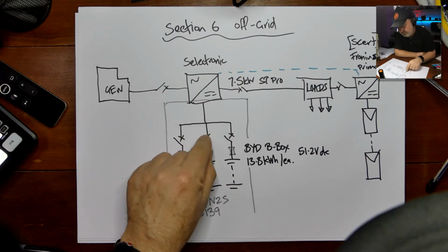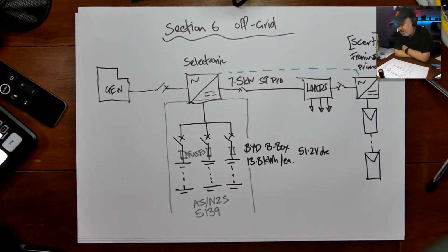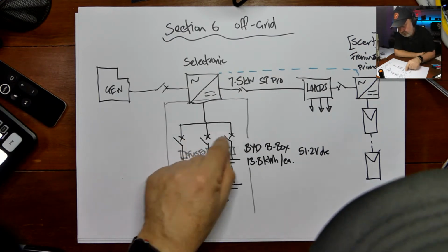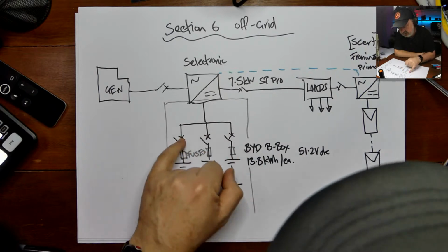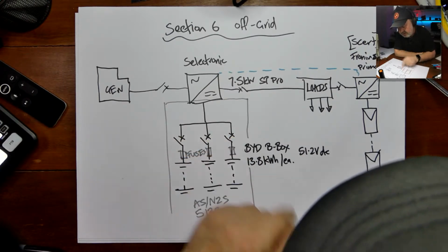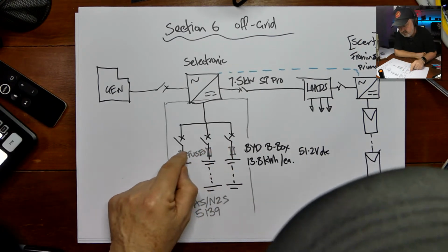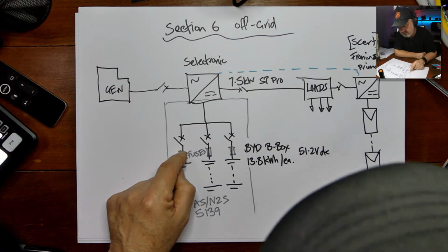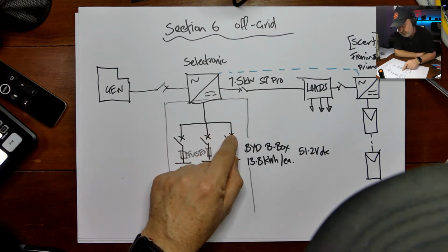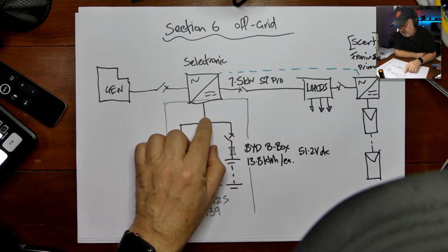Now, I didn't have to actually add 3 if there was an accessible switch in each one, but there isn't. And so I could parallel those together and have 1 switch, or I could have 3 switches. So I've drawn one option here. If I parallel them all together, the fuses provide the string overcurrent protection requirements that we have in the standard, and the isolation requirements could be those 3 separate isolators, or if we parallel them, a single isolator.